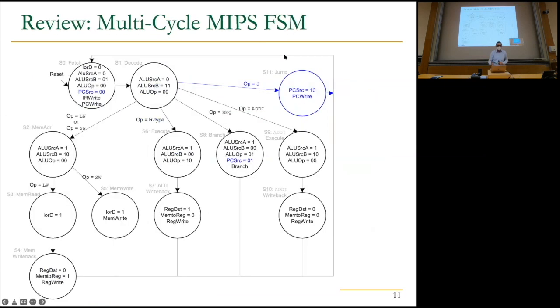And this is a finite state machine. It's much more complicated because now different instructions actually follow different states, if you will. This is fetch over here. It's one state here, but you can break it into multiple states as well. This is decode. And then different instructions follow different states after that. And then we discussed trade-offs related to it. What is the shortcoming of this design? Well, first of all, the upside is you could keep adding instructions to this finite state machine by adding states, by adding data path elements, and by adding control logic as you need to execute the instruction.